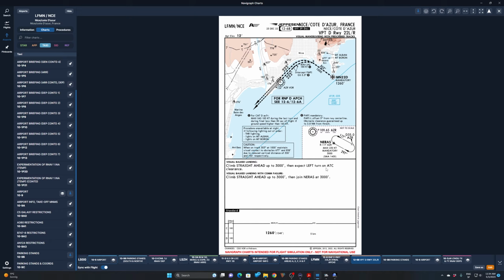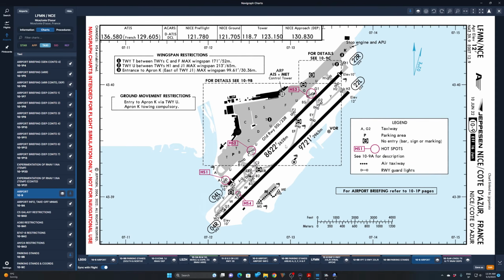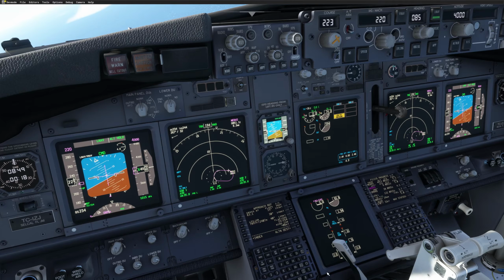So that's quite straightforward. We will use auto brake 2, flaps 30 for landing. The runway is very long. We have no issue with the runway, about 2,600 meters, so that should be fine. And we will stop on the runway to assess the aircraft. Good. Any questions? If no question, we will prepare then the cockpit.